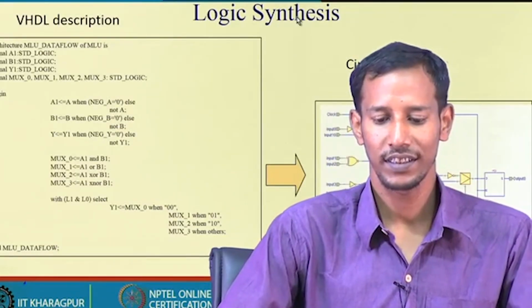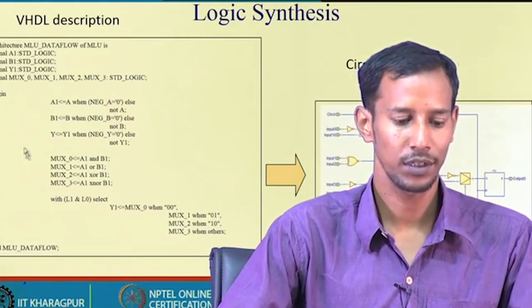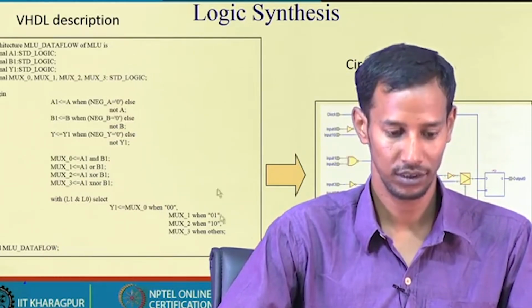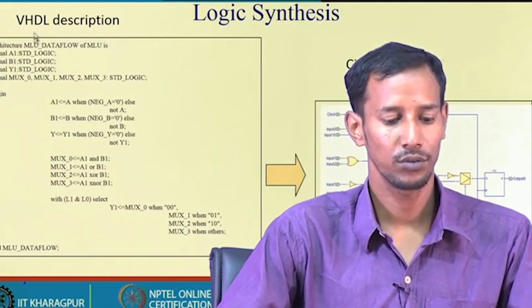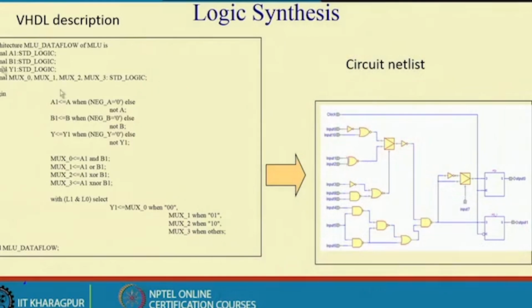So, logic synthesis is this: here is the VHDL code, the logical expression which I have written using the VHDL language, and this is the corresponding gate level netlist, the circuit level implementation of the circuit which I have described using VHDL.